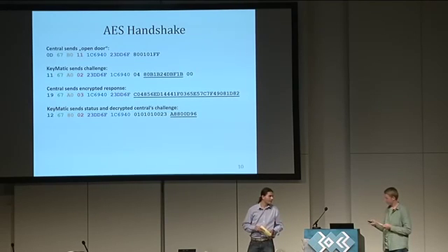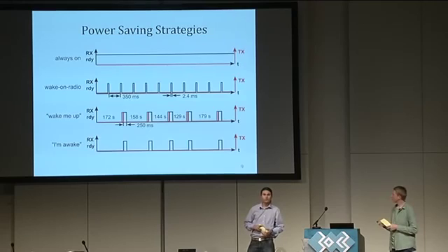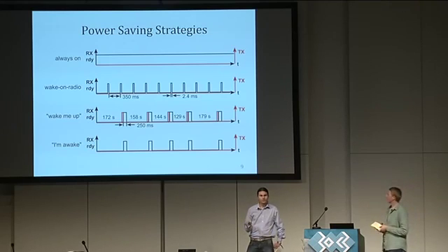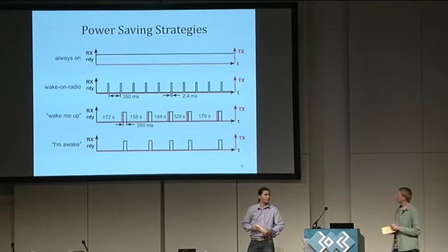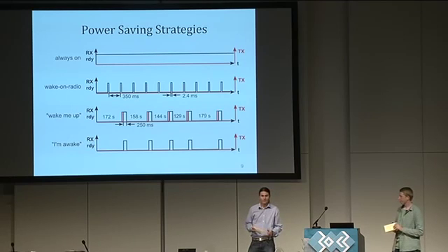One slide back, please. The receive ready mode draws about 14 milliamperes of current, so that the battery would be empty in about 1 week. So if you use a wake on radio mode, the average current draw is reduced to about 100 microamps. And the other modes reduce the current draw to about 20 microamps, plus additionally the current draw of the motor and the microcontroller, so that the batteries can last 1 year or even longer.